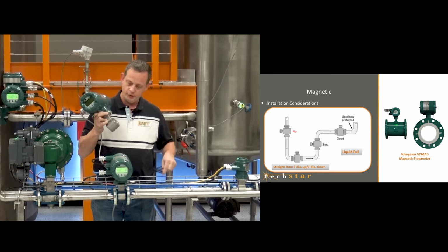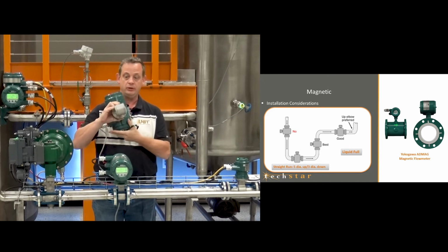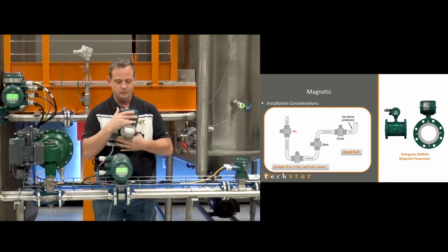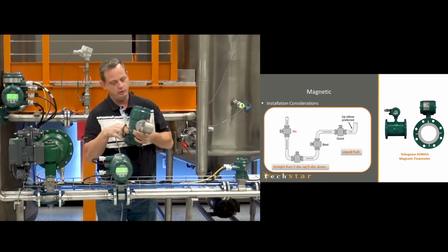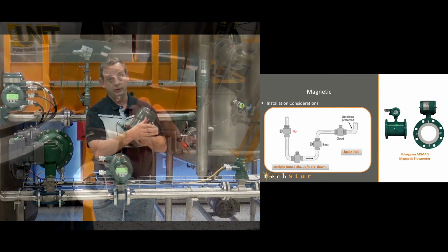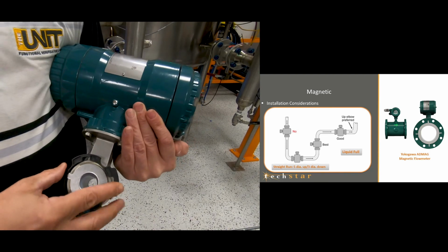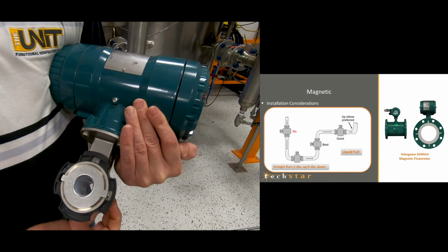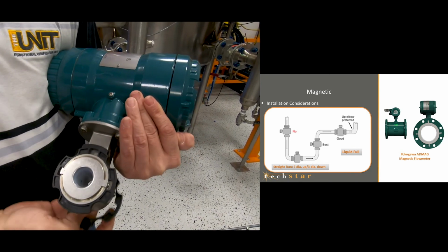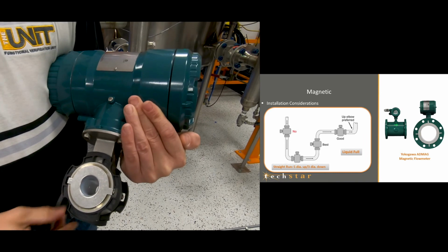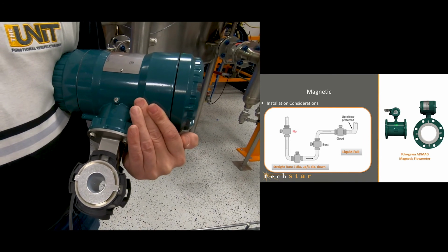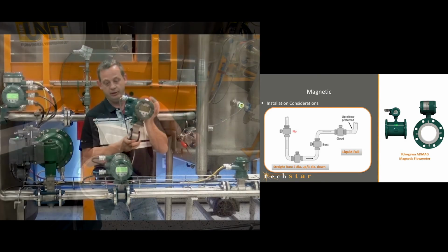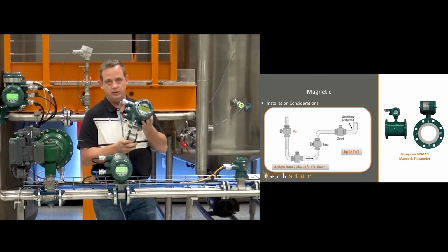And if you're dealing with a wafer style, this is a wafer style meter here. You also have flange style. Flange is not too hard to understand, but on a wafer style, we want to install these centering rings, not grounding rings, like this. And then you put them on the other side too. What this does is ensure that whenever you mount it and you put your bolts through, you're basically just lined up in the pipe properly, because you don't want to be off center. So this helps you get it lined up. You can leave them on there, you don't have to take them off. It just kind of lines you up.